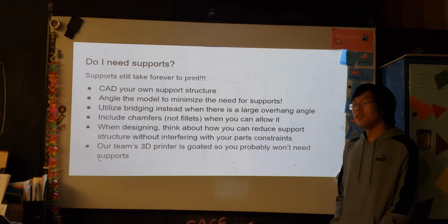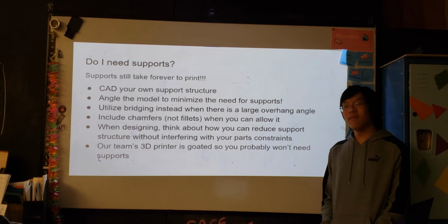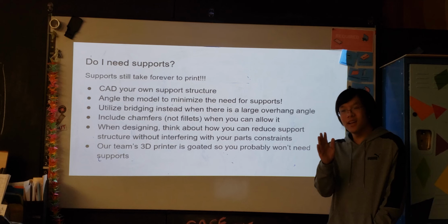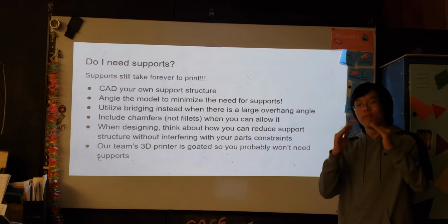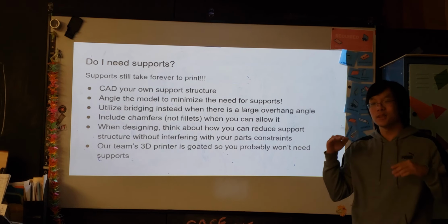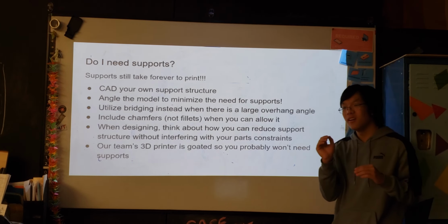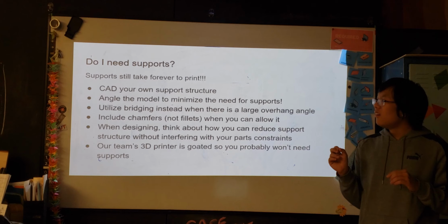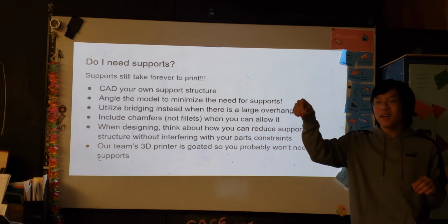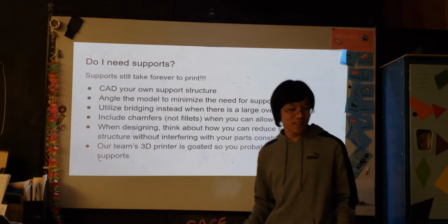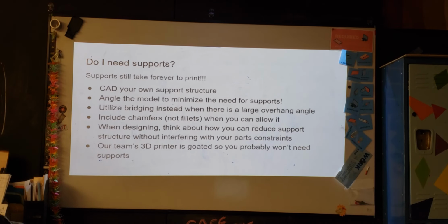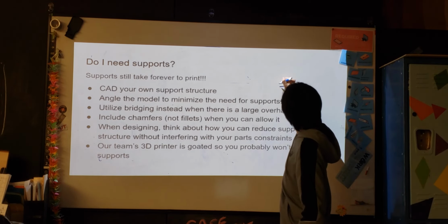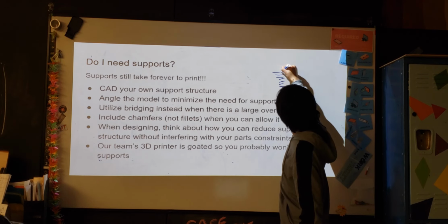So this is kind of hard to explain, but if you 3D print something with like an arch, it'll actually be worse to print it with an arch than to just bridge it at a 90 degree. So if you print something at an arch, the layers will look like this. Here's a marker. The layer will look like this, right? This is the wall, and then it'll start arching, right?